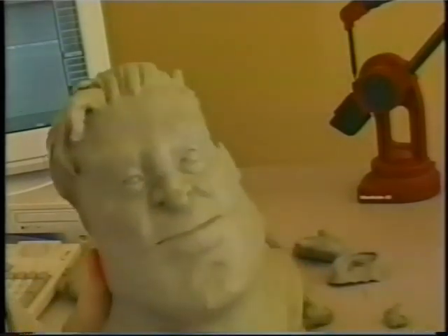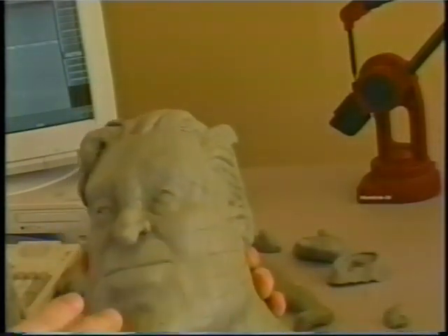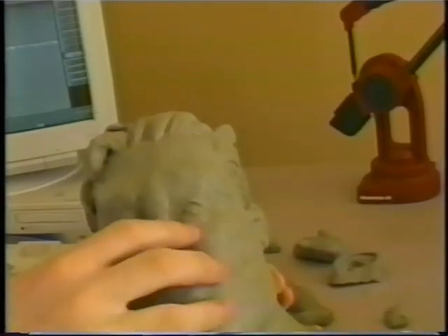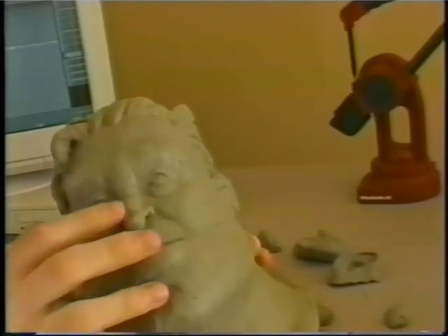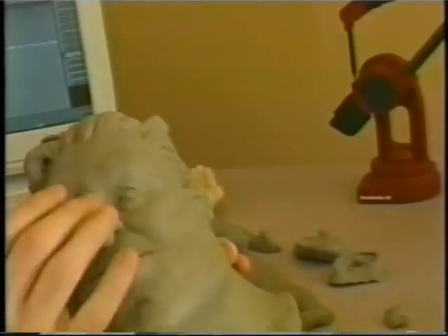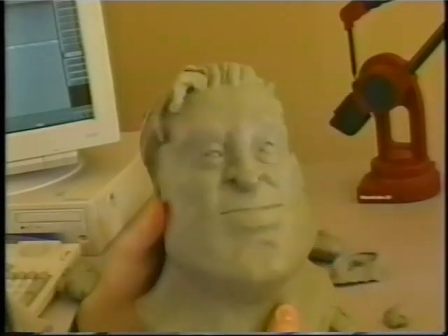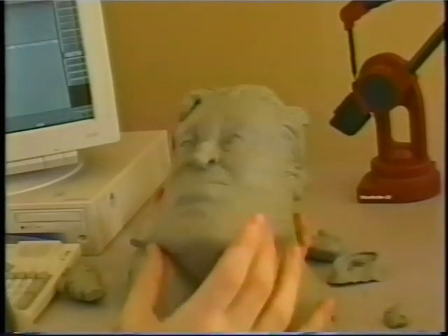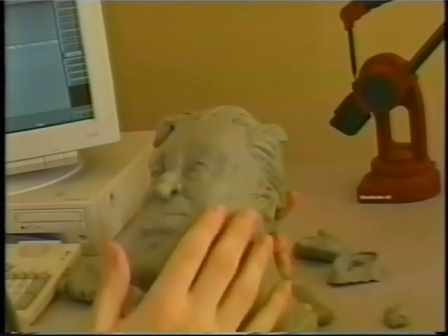Now, in the model that I include, I actually just use shrink wrap. I just use shrink wrap on the edge points of basically this patch here that goes over, or this NURB surface that goes over the underneath portion of the nose and stops. So this is a separate area, and the same for the eyes. They're separate square NURBS patches. The layout was designed for basically the edge suction plug-in or something along those lines, where the underlying surface, as it updates, then the edge points all along here will update with it, and so you'll have this smooth connection that continually updates.